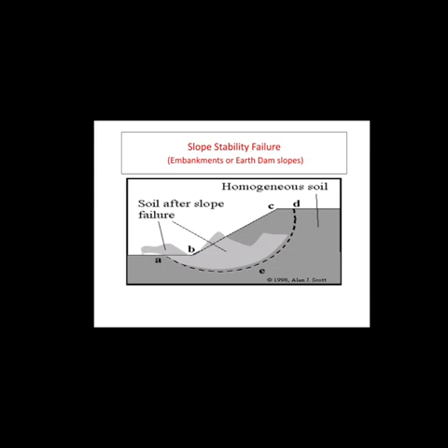embankments. It is noted here that under any given critical conditions, the soil mass in a slope fails along a circular surface such as AED. The mass of the soil bound by A, B, C, D, E, A moves under the action of gravity, thus shearing or cutting it off from the rest of the soil mass. We need to evaluate the shearing stresses and shear strength along these curved failure surfaces.